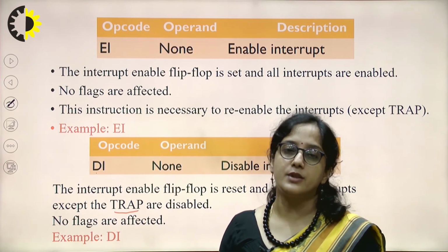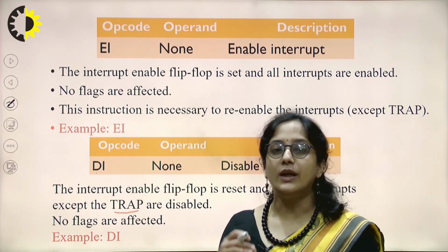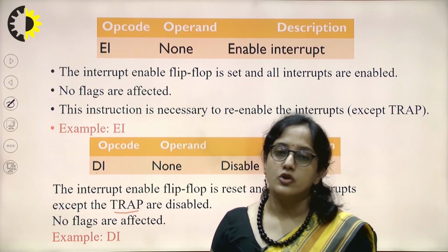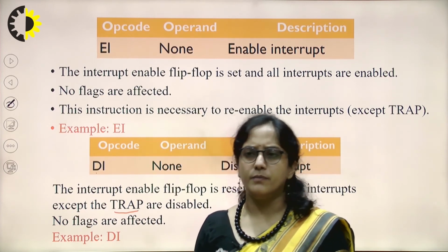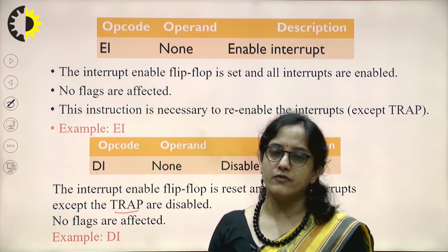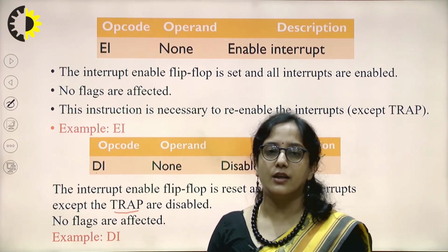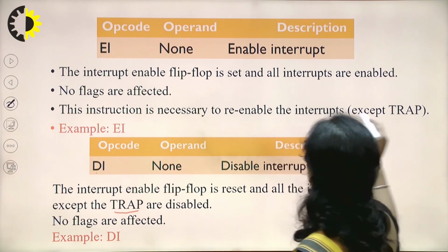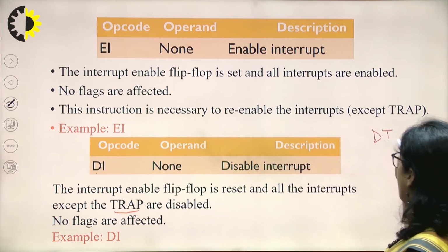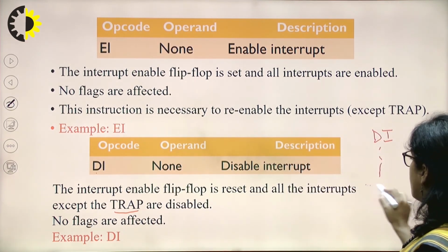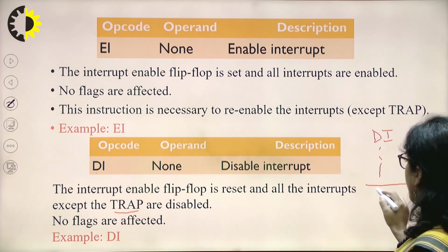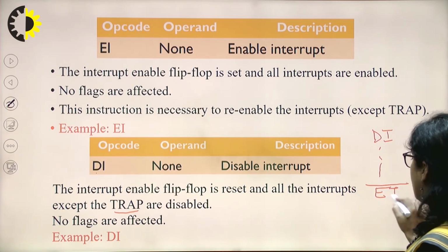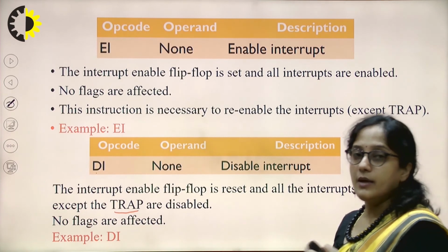The rest of the interrupts are not able to interrupt the main function. So if we have to perform some main task, and in that task we don't want any hardware circuitry to interrupt the microprocessor functioning, then in our main program we can write DI first, give the task to the microprocessor, and then write EI to enable the interrupts when that task is completed.